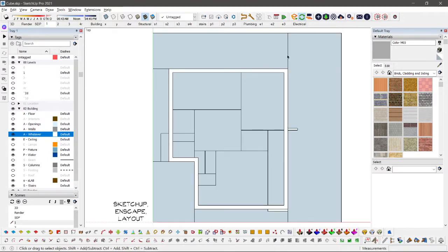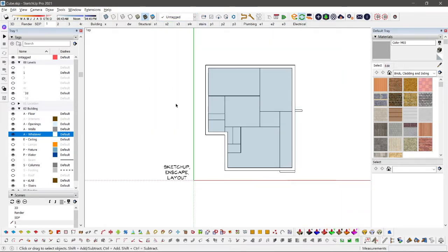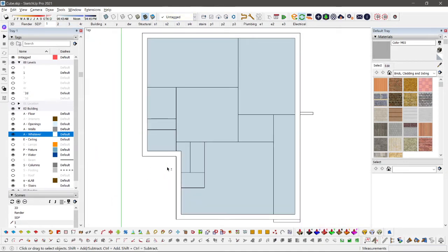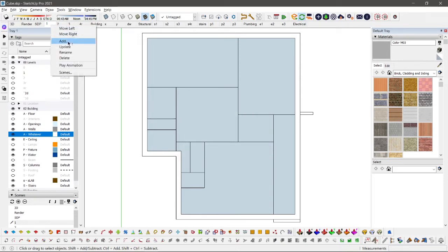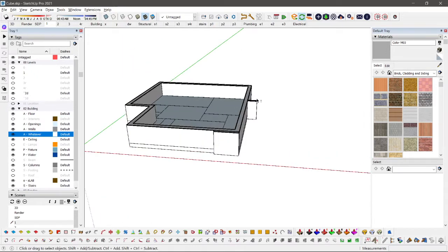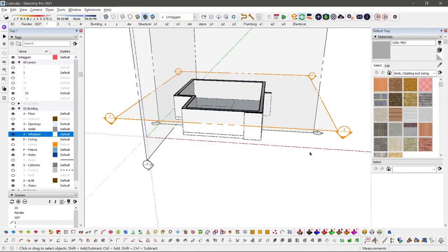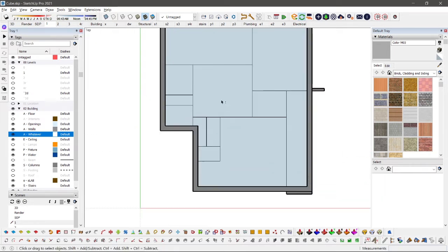So for the site, let's put it under location site, so we can only see the first floor. Alright? Shift Z to zoom to extents, Shift 3 to update, or go to the scene, right click update. However, we have to turn on our section cuts, so enable the section cut according to your volume 2, and you could adjust the section plane. Okay, in this case I'm going to start to make some holes or openings.